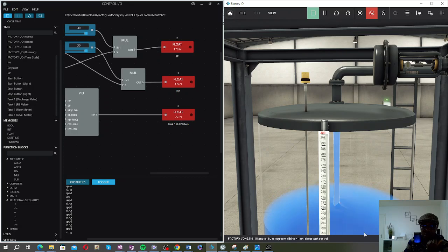It has opened. Now, if it's too exact, the frequency of opening and closing will be very, very high, and this thing will pack up in no time. So that's why you have to give tolerance. Like in the example we looked at before, we talked about 75 to 85% conversion, and that is enough tolerance for you to keep the health of your pump and your control architecture.